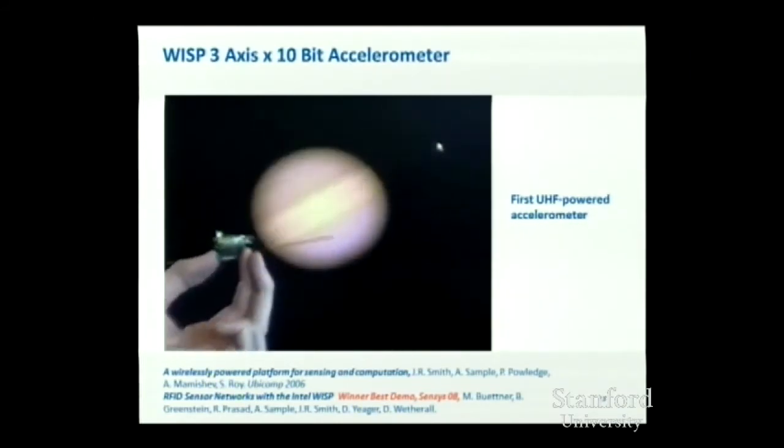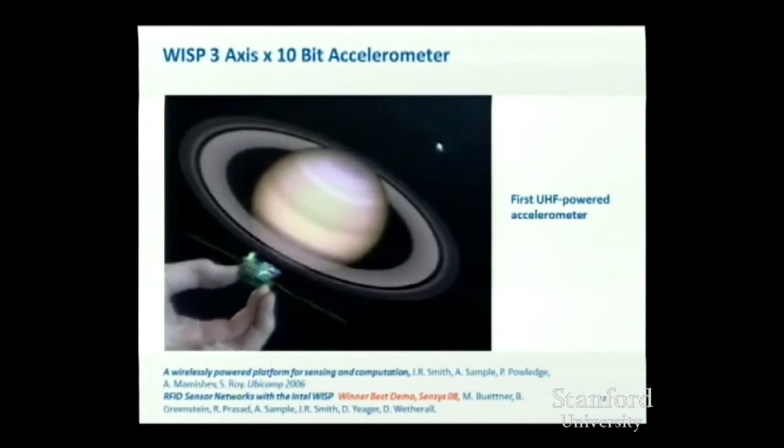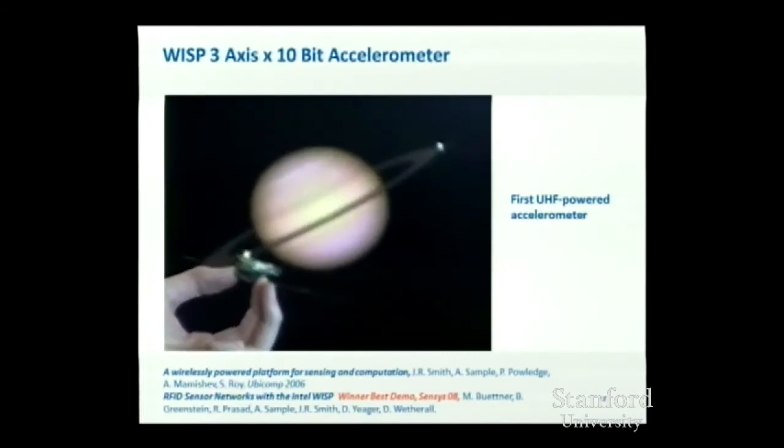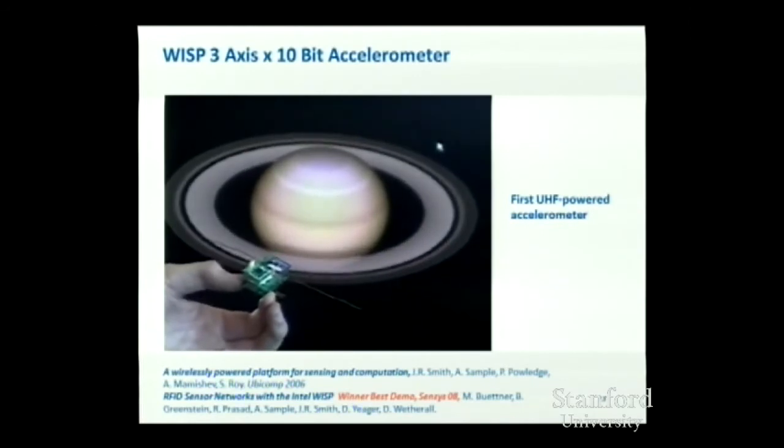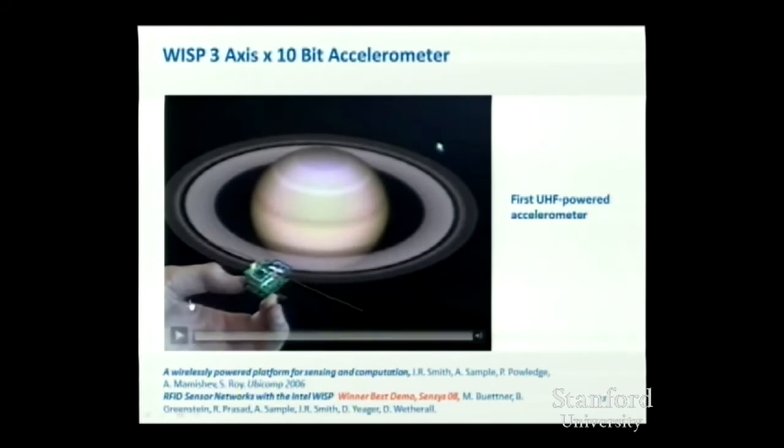Again, the key interesting thing about this is that there's no battery in that stack of boards. And the other thing I should emphasize, sometimes people look at this and they think it's some kind of antenna polarization trick or something like that. It's nothing like that. That's a system that's being powered by the RF, and it's digitally communicating via backscatter.